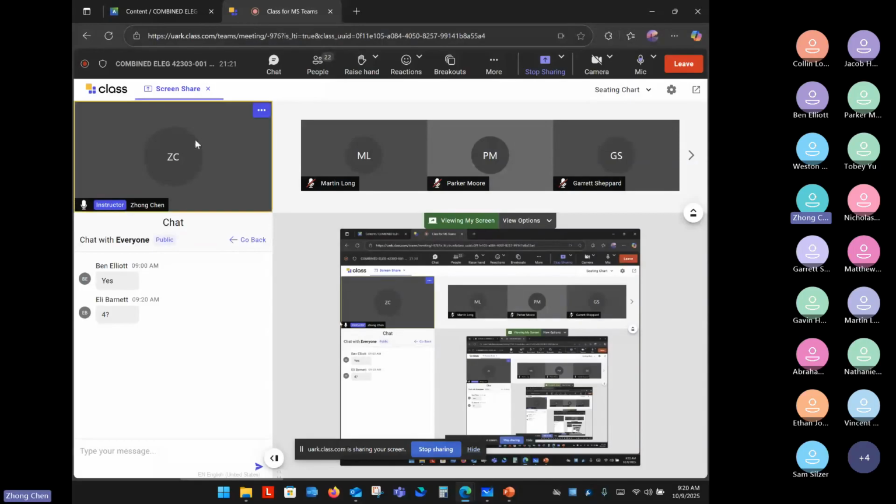Yes, that's four inputs, right? That means the gate is connected with the four inputs. So the PMOS gate and NMOS gate are tied together, right? So four inputs means you have four PMOS and four NMOS, all right? The next question is, for the NAND gate, is PMOS in parallel or in series?